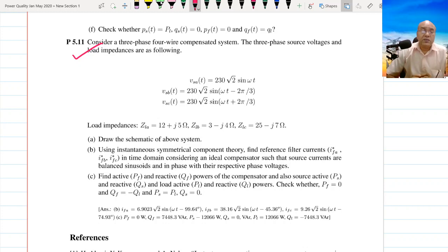It is called DVR, or dynamic voltage restorer, which is a complementary device to D-STATCOM. D-STATCOM, or distribution static compensator, compensates the load currents by connecting it in shunt with the load, while DVR does the dual function, the opposite of this, that is, it compensates the voltages by connecting it in series with the load to ensure that the load bus voltages are maintained at the nominal or standard value and their nature remains sinusoidal.